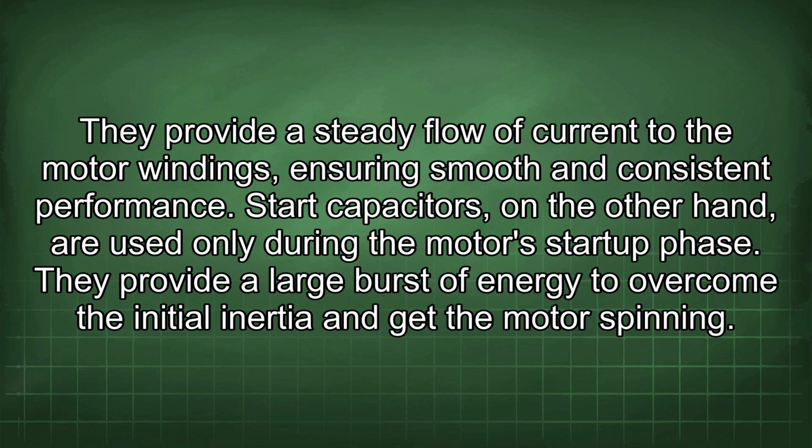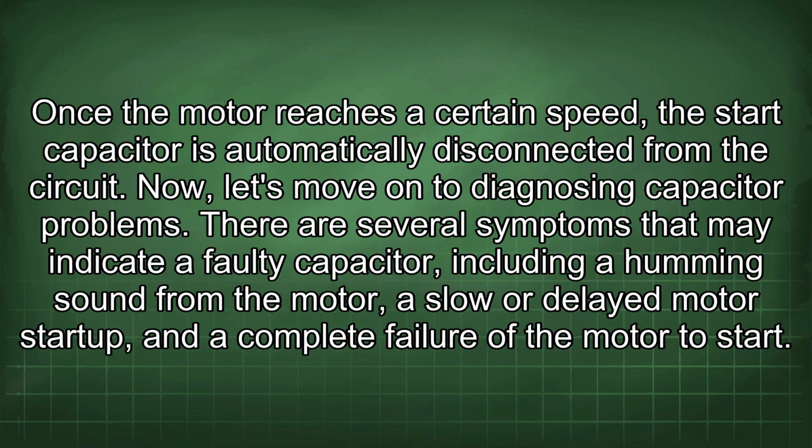Start capacitors, on the other hand, are used only during the motor's startup phase. They provide a large burst of energy to overcome the initial inertia and get the motor spinning. Once the motor reaches a certain speed, the start capacitor is automatically disconnected from the circuit.